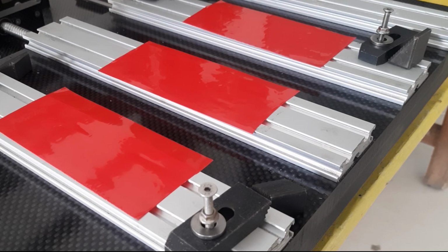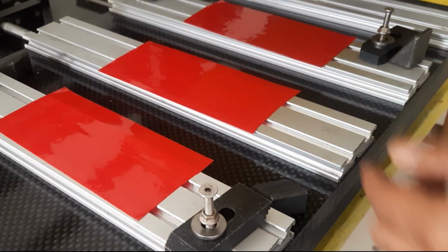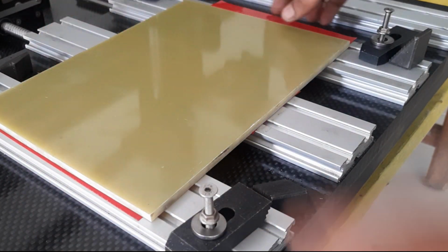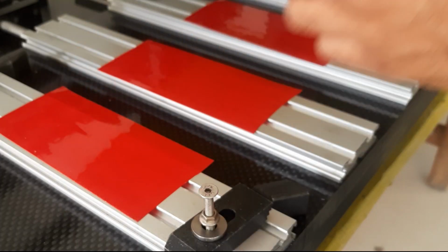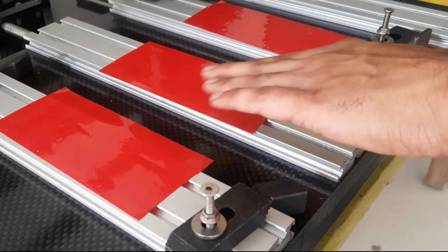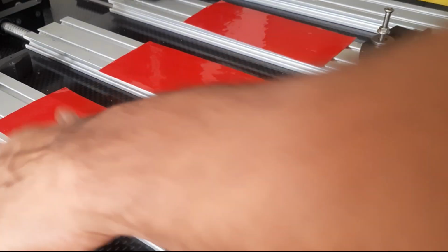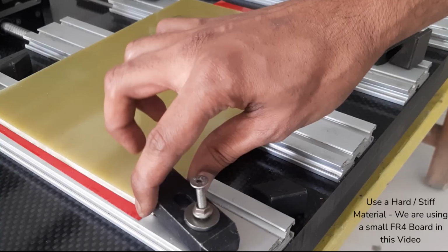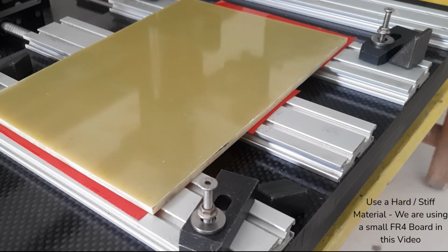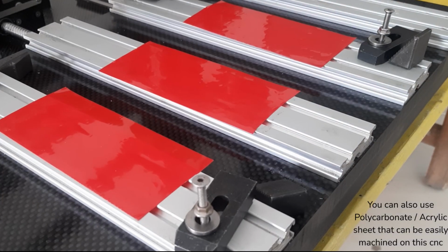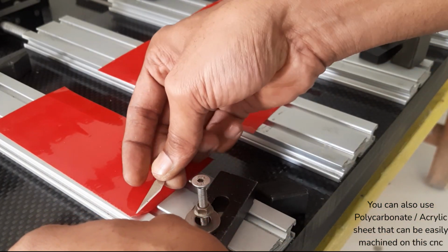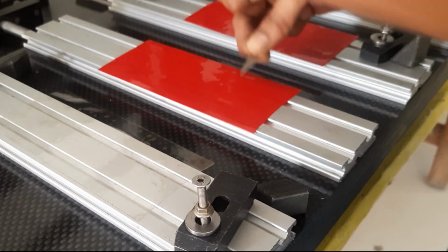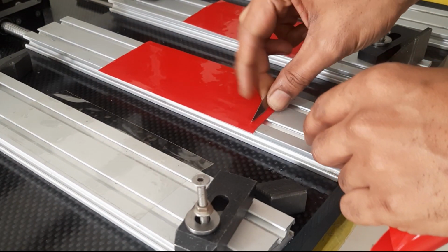We are not going to directly have the PCB copper clad mounted on the CNC machine. We always use a wasteboard. In this case, I am using a 6mm fiberglass sheet, and the way I am clamping this board is to first stick it onto our base plate using double-sided sticky tape. I then clamp them using steel clamps, and the reason I do this is because if we only clamp the surface on a board like this, it's possible that it bulges around the center. So in order to prevent the board from bulging and moving around, we stick it and then we clamp the board. Also notice that the operator's hand is quite hairy.